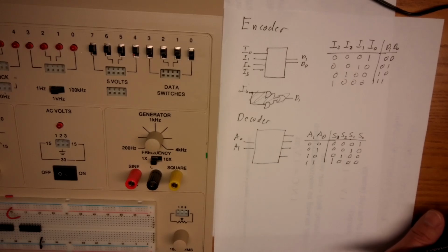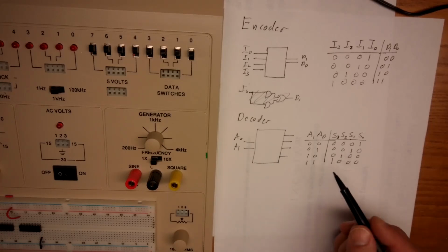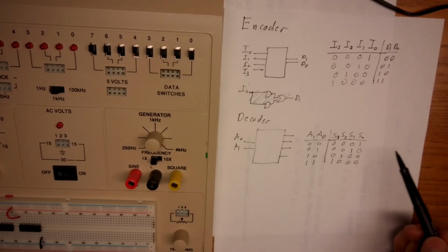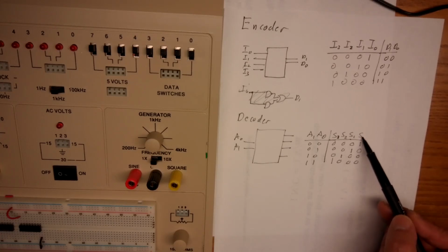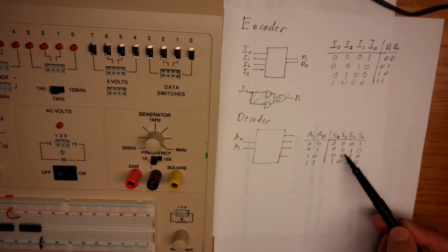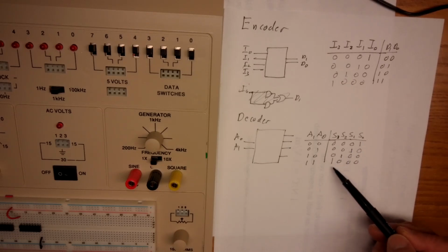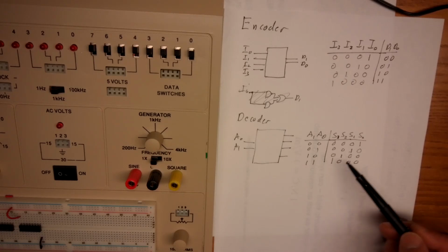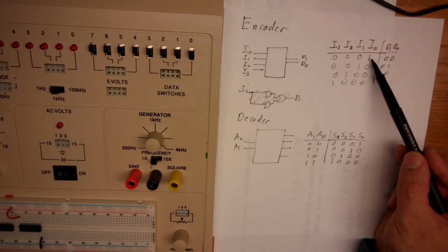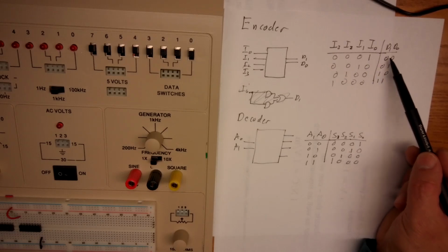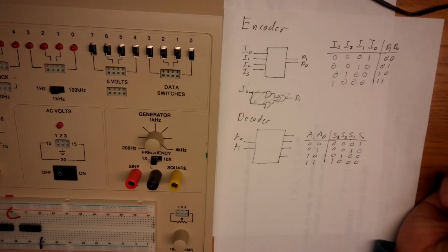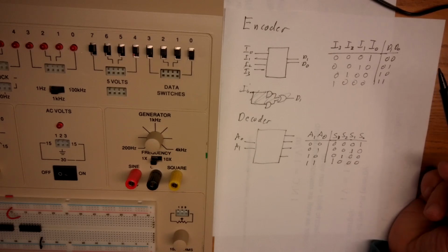So in a very simple computer, we might have our CPU put out a number that says, we send a signal, maybe we set S0 to the mouse, and we send the signal off to the mouse, saying, hey, do you have information to give me? 1 might go to the keyboard. The 2 might go off to an input like a USB or something like that. So we could use that in this simple example to poll each thing we have. The reverse can happen too, where something receives information, it will set itself to 1, and then we see that come in and say, oh, that device has something ready to go. That'd be a simple use of our encoder and decoder.